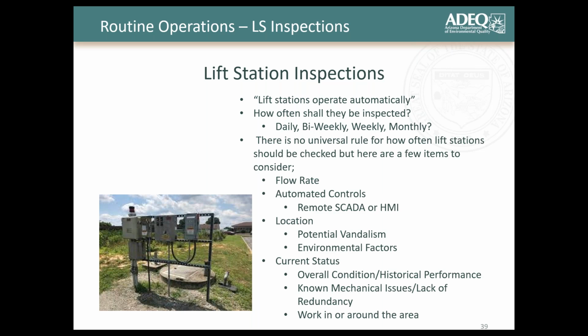Now here are a few items to consider when you're determining how often you're going to check, right? If this is a bigger lift station with higher flow rates, you may want to be there daily. This is a high priority lift station. If it's a lower flow rate lift station, you can probably take your time and maybe not be there as often, right? Lift station failure may not necessarily back up.